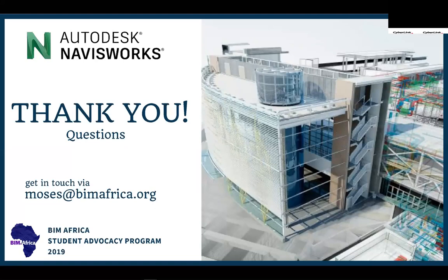There's a question from Azan that can you use Navisworks Manage for cost control or management? Like I said, the functions there are basically for quantification. The function of quantification is for determining the quantity. That's why we export to Excel or other suitable means to be used for other estimation tools.